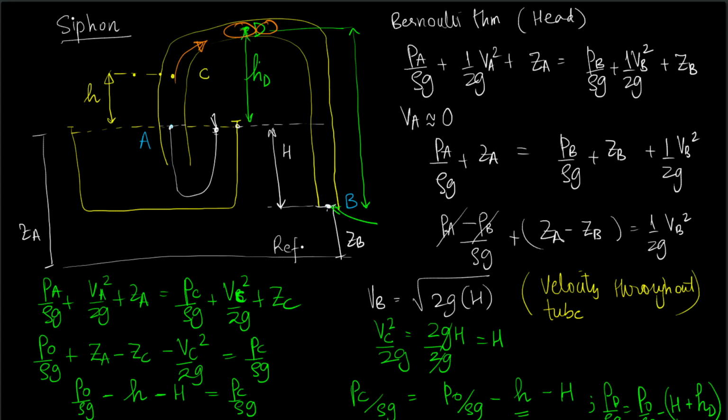But if the vapor bubble starts to move, at a certain point, the pressure will again begin to rise, because we know that the pressure over here will be atmospheric pressure minus this particular height as found from the equation. So the pressure again will increase, and once it exceeds the vapor pressure or allows for a larger solubility of dissolved gases, the vapor bubble or the air bubble can again go back into the fluid by collapsing, and this collapsing process is often quite violent.